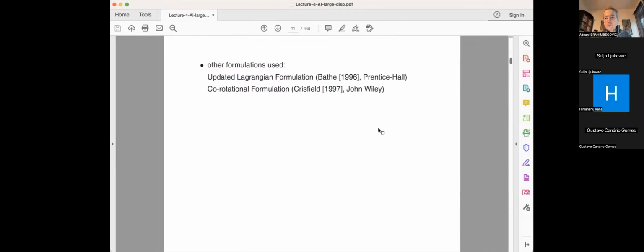So even though you are having large displacement that takes you into a very different deformed configuration, you are going to do this in an incremental way. So you take these increments, and in every increment you move your frame, and then you apply the Lagrangian formulation for this particular frame.